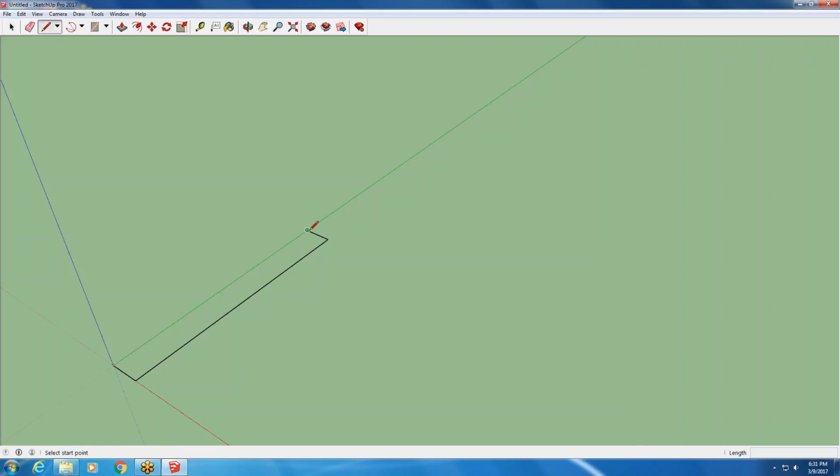Even though it said there was a line, once you deleted the face, it pretends, it's kind of like a weird algorithm, that there's only 3 lines here and you just need to close off one of them. Now if I do that, because there was already a face there, then there's 2 lines there. But it makes them one because there's only one face. It's really strange to think about and you'll get used to it. So you're not going to have stacked lines. Just imagine if it's on the same plane in the exact same spot, it exists only as one thing.